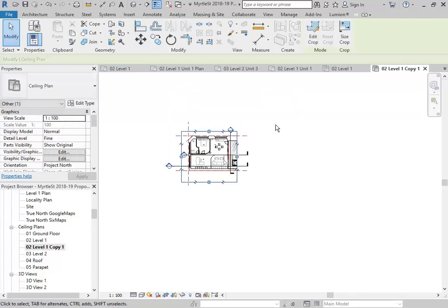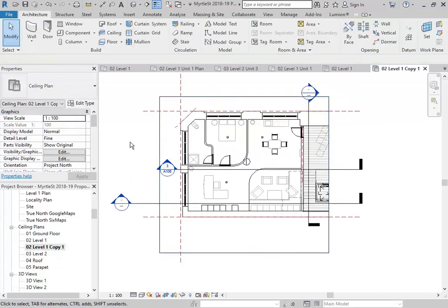So the key thing to realise there is that it's a reflection. So it's not a true ceiling plan, but just to give you a tip, no one does true ceiling plans. A ceiling plan would be a mirror image of the floor plan, because you're cutting through and you're looking in the opposite way. So if you opened it up, it would be a mirror. And it might sound like a useful thing, but it's actually not really that useful to have a true ceiling plan. It's much easier to have a reflected ceiling plan because it's oriented the same way as your floor plan. So, complicated to explain a reflected ceiling plan, but it's actually much easier to work with.